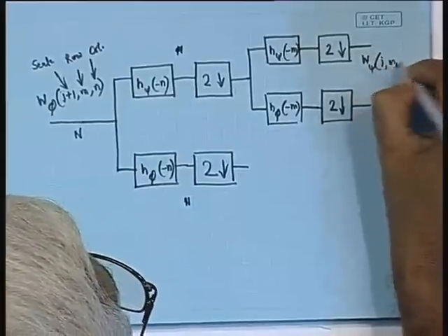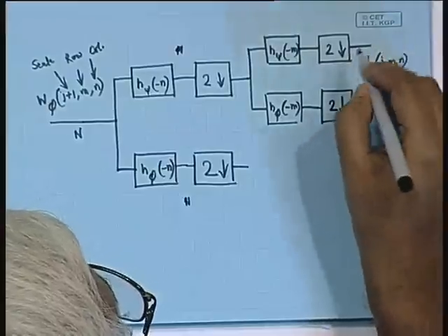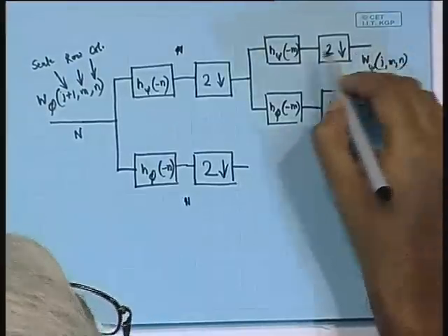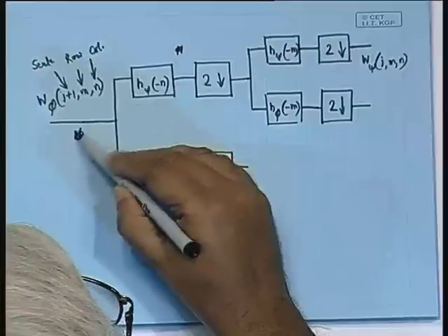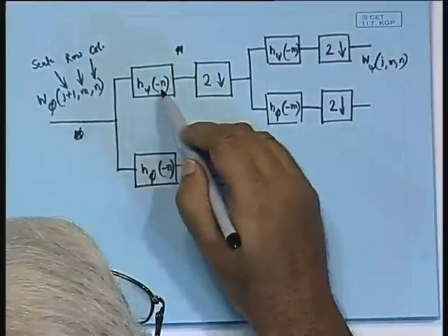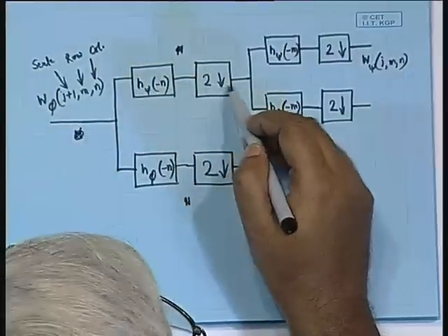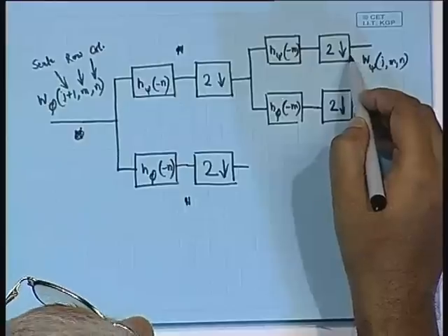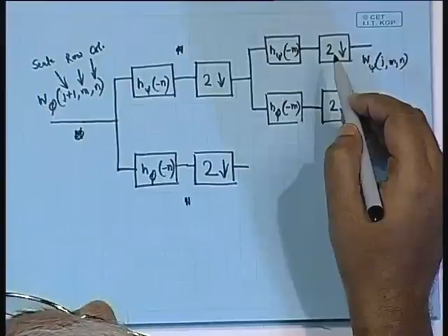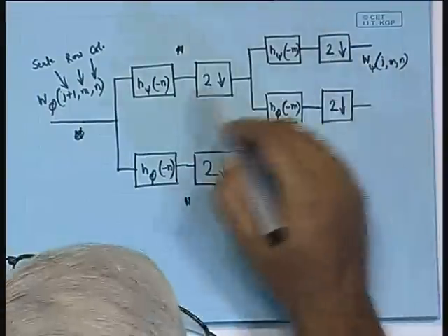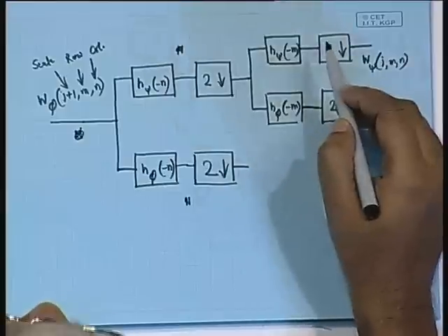J m n, and just look at the nature of this signal. This signal we are deriving by high pass filtering along the column and high pass filtering along the rows. Which means it is extracting the high pass along both rows and columns, which means HH. Basically, the HH subband is being referred to over here, and high pass filtering extracts the edges.